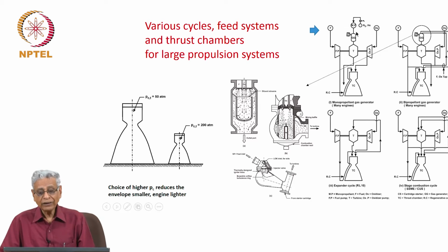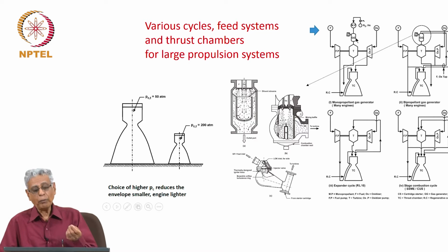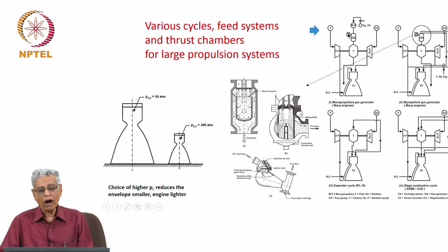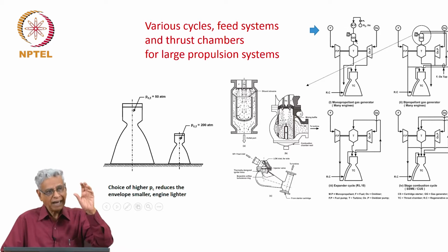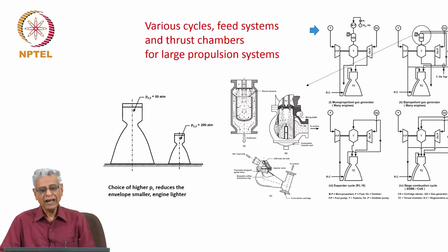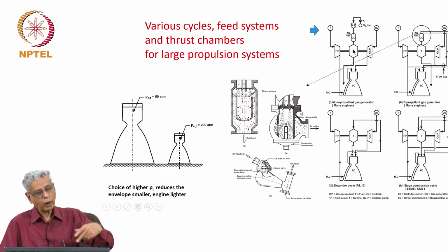And for that, you have to pump the liquids. Normally by gravity it starts up. Or you start up using a solid cartridge to spin the turbine. As this turbine spins, it starts pumping and starts feeding liquids back into the gas generator. Gas generator starts stabilizing, and once it stabilizes, the RPM of the turbo pump increases and things like that.